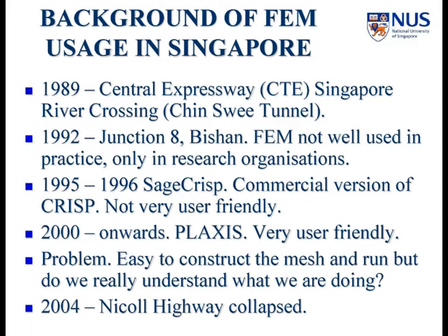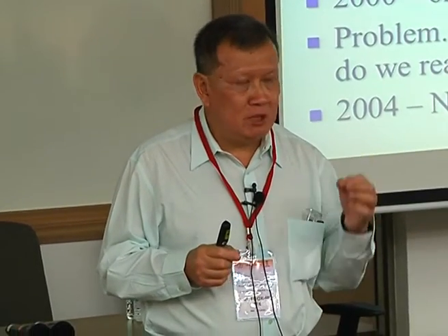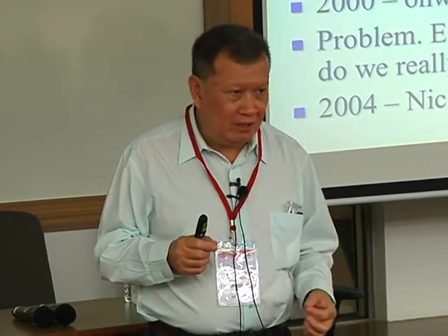Now, when this started, the Mass Rapid Transit Corporation also got guidelines relating to digging a big hole in the vicinity or proximity of, or neighboring, an MRT. For those of you who are going to work in Singapore, this may be important, because I know that there are many Indian graduates working in Singapore. If you build something next to a station or station box or tunnel, whatever it is, the rule is very strict. No part of the MRT structure must move by more than 15 millimeters.